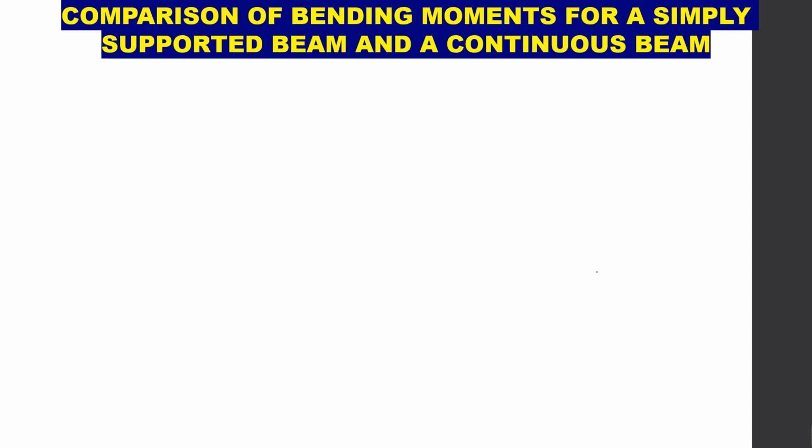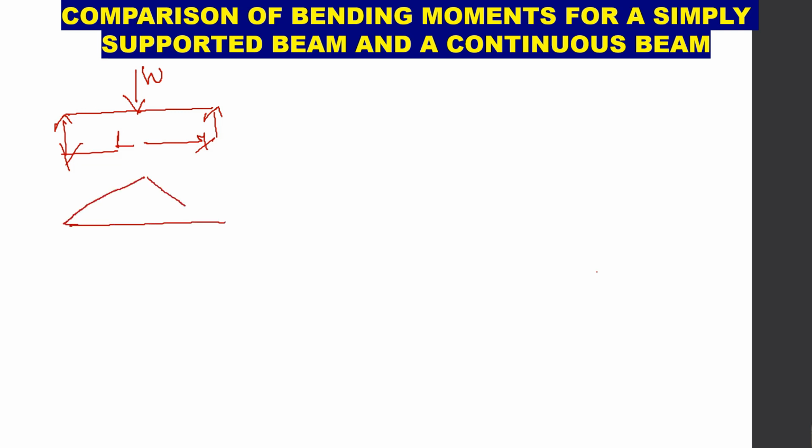Now let us see the comparison of bending moments for a simply supported beam and a continuous beam. So for that we will take a simply supported beam first. For a simply supported beam, when it is subjected to a single concentrated load of W, we know the bending moment diagram for such a beam is WL by 4 at the center, and it will be 0 at the supports. At the supports there will be 0 bending moment because of simple supports.